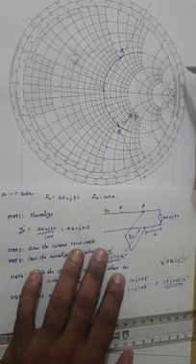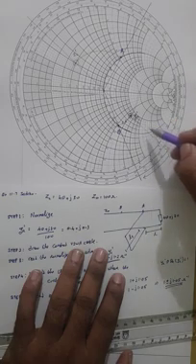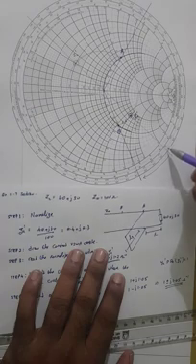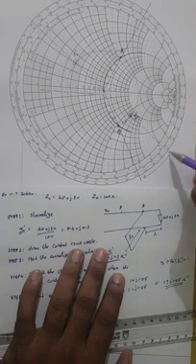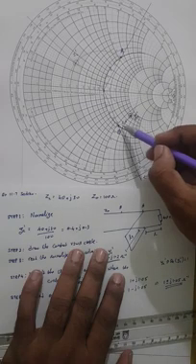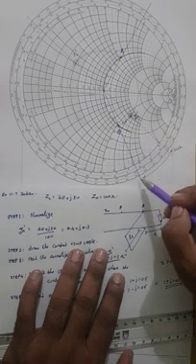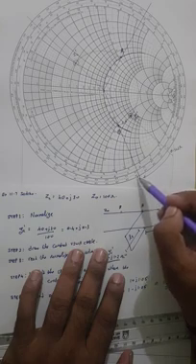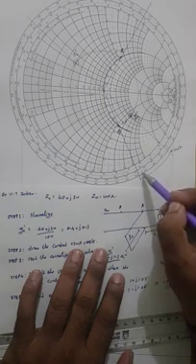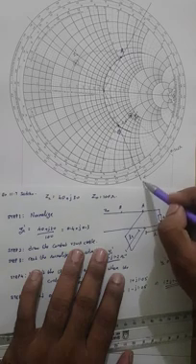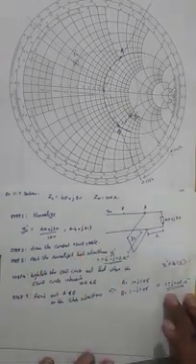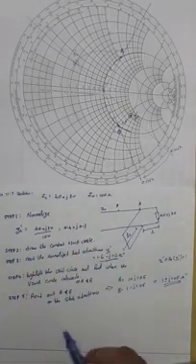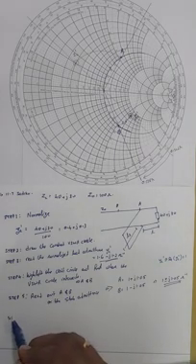On the outer scale, we measure our load to be at this point: 0.3, this is 0.31, so 0.302. This is 0.302 lambda. B is at 0.33, 0.34, so 0.332, 0.334, 0.336, and 0.338. 0.338 lambda. So my spot B, let me call that YB. I can compute the distance.